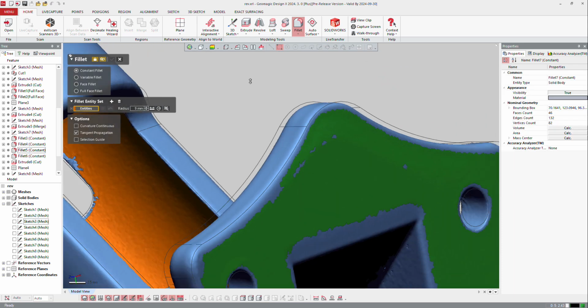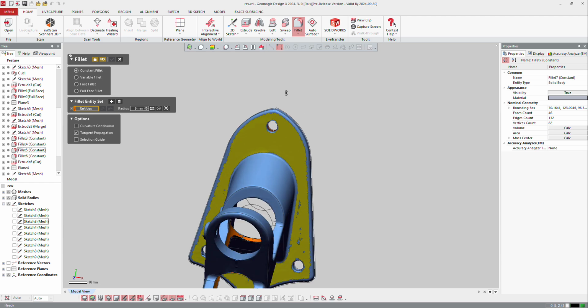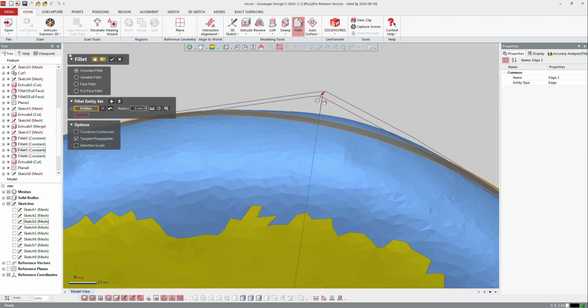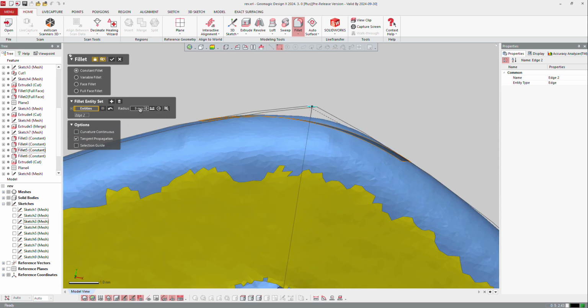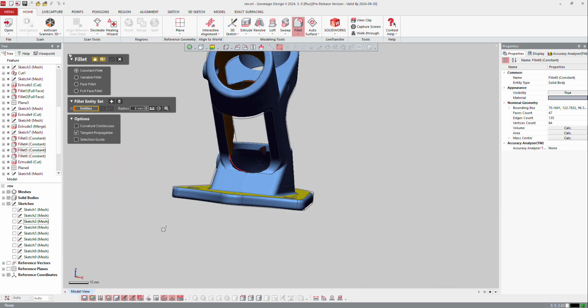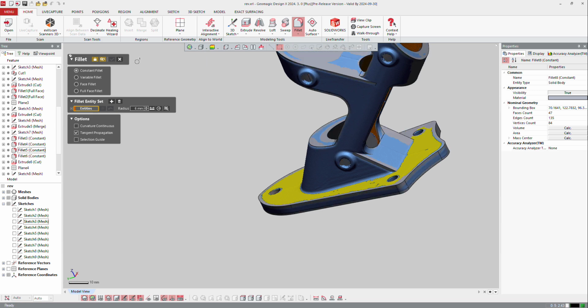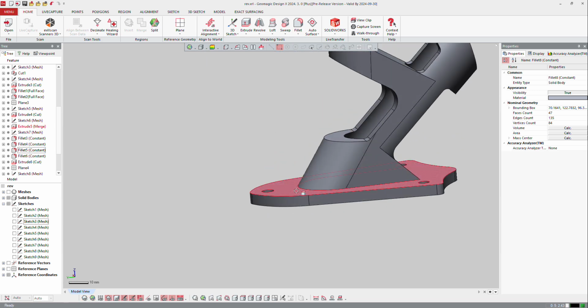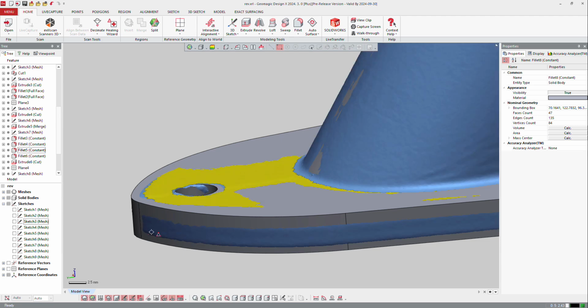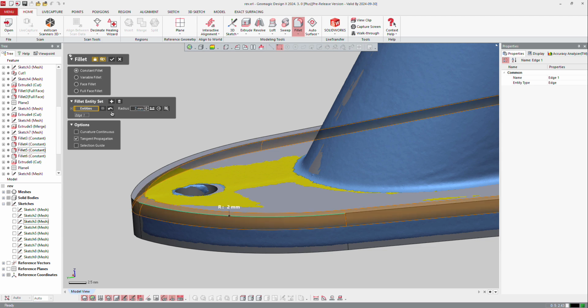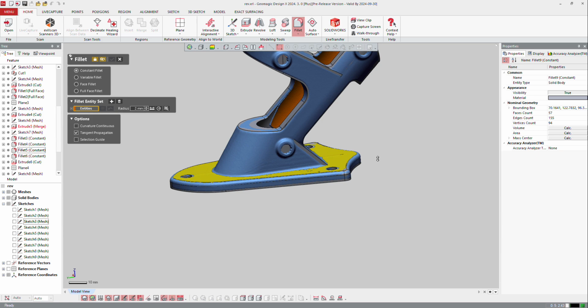And all right, let's do the same on the other side, because on the other side we did the same thing. We didn't create a nice transition. So here, and you see it's too much, so maybe 6. And okay. All right. Now if I switch my display and display the CAD in real CAD and hide my points, I can maybe display here and make a fillet there. So the fillet will turn around, but if it's possible, so if I make 2 millimeters, of course it can turn around all around the part.